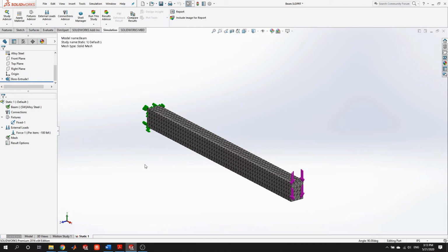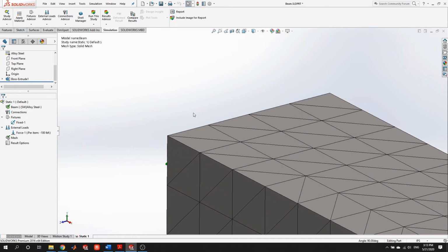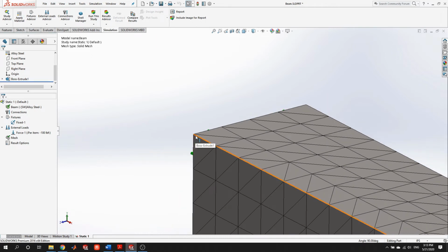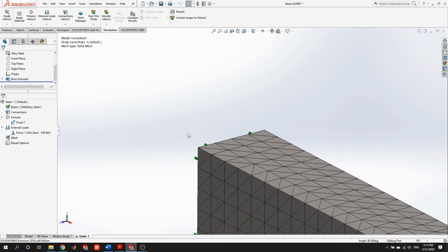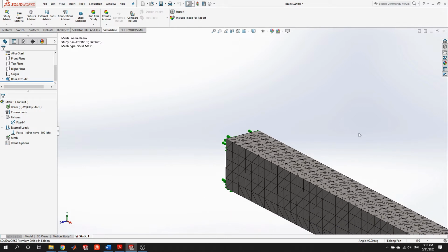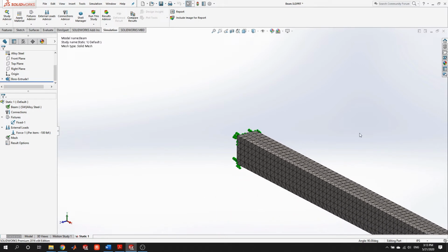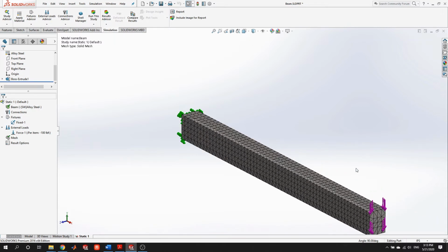We do have a problem here. In the case of our beam, right against the wall, the way we fixed it, we will get a stress that will continue to increase as we change the number of elements. This is, of course, not what we want. If you ever see this behavior, this can be indicative of a really sharp edge or reentrant edge where the results can't be valid because as we change the mesh, the stress changes. We can almost make the stress anything we want by setting the number of mesh elements to a certain value. This is, of course, a numerical artifact, but sharp corners are oftentimes not good in a real structure.